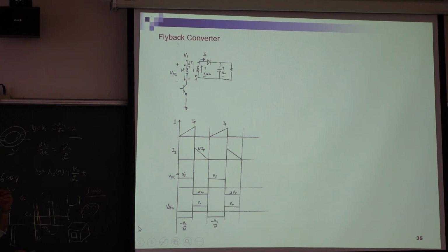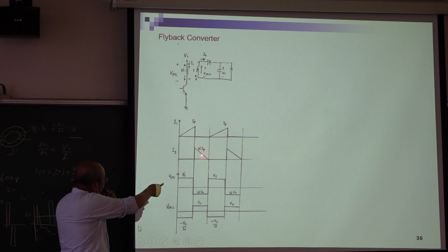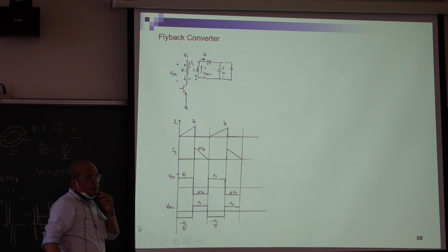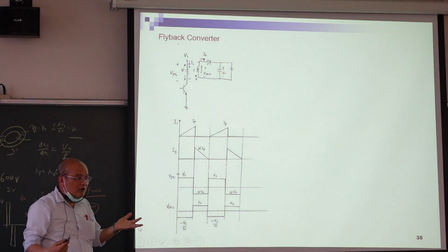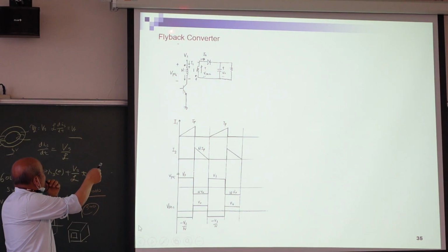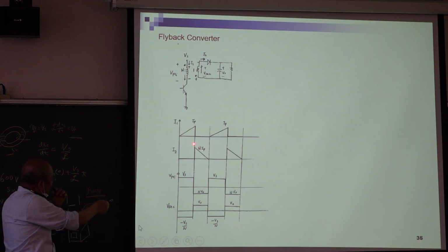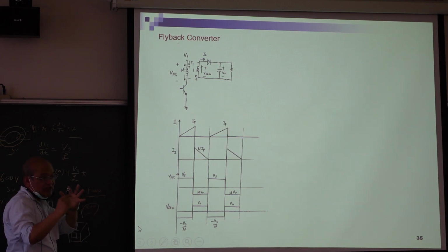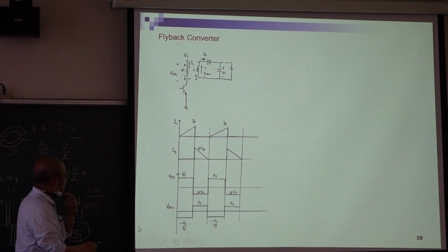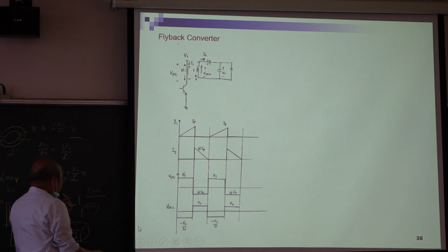So I have a question. If your current has not reached 0, can you turn on the switch? Yes or no? No, because this flyback converter should guarantee your current reaches 0, then you can turn on. It should be discontinuous, right? Discontinuous. So you can see this waveform.